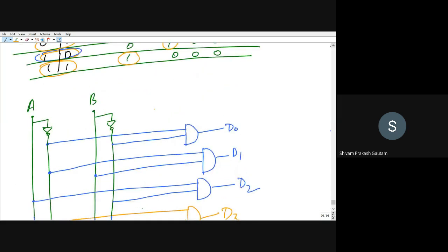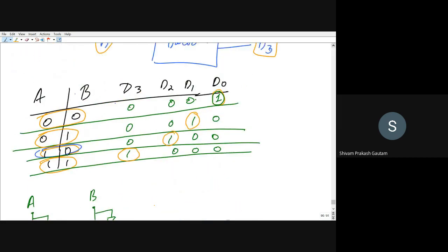For example, if I want to write enable here as well, if I want to add one more column here, like enable, then enable should be high in all the cases for getting the output lines. Now, when enable is low, for any combination, cross means we do not know, so I can write cross here. For any combination of A and B, we will not get any output.